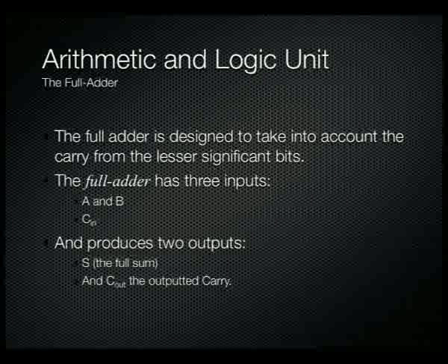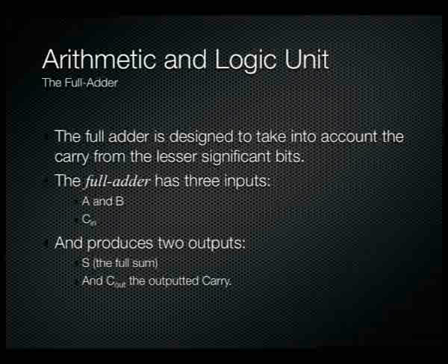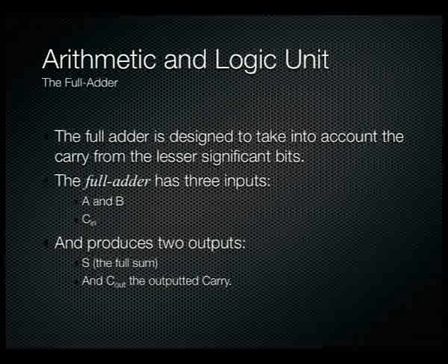So the carry bit from lesser bit additions can actually pass into this full adder. And it produces 2 outputs, like our half adder: the result, the full sum, as well as the carry out, which it can then pass up to more significant binary additions.